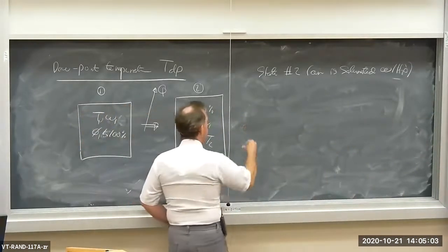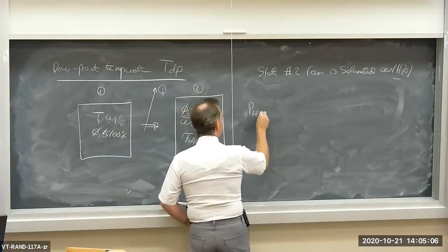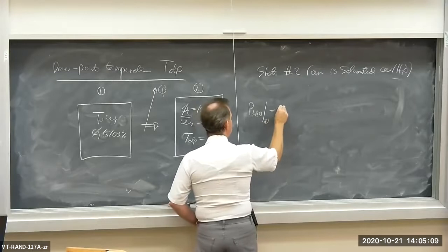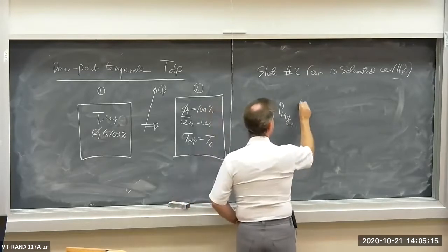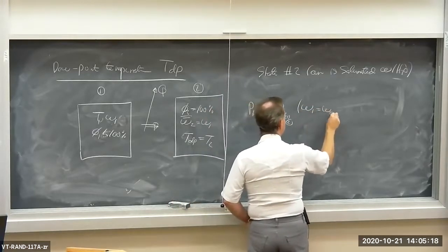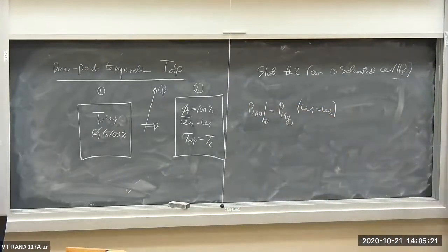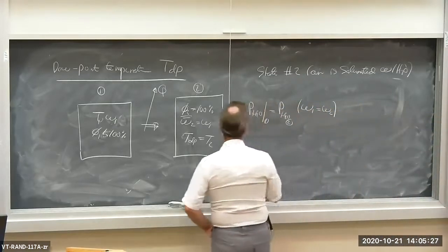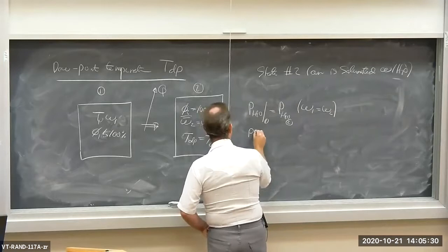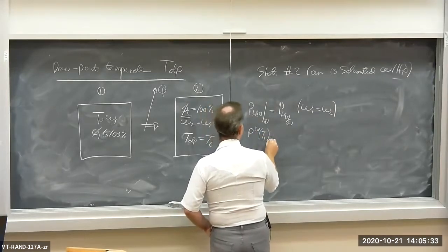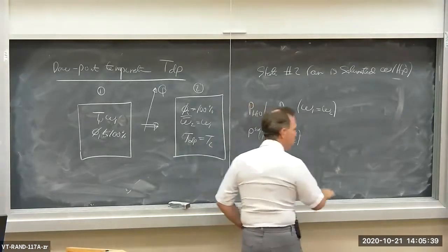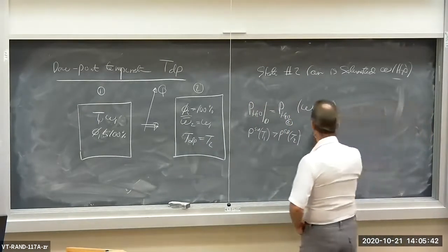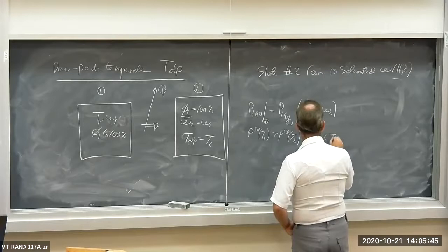So just to remind you here, the partial pressure of the H2O at state 1 is equal to the partial pressure of the H2O at state 2. Why is that true? Because omega 1 is equal to omega 2 here. I'm not adding any moisture or any dry air, so the absolute humidities are the same. But as temperature goes down, Psat at T1 is greater than Psat at T2 because temperature is falling, okay? Temperature 2 is less than T1.